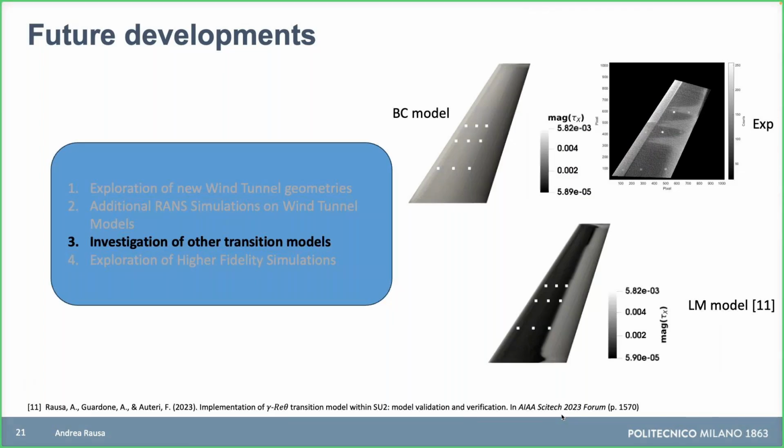Well, it depends. If you use the vortex lattice method or panel methods, then it's a matter of seconds, because they are potential theories and they do not require any other simulation. So you just have the grid. If you use the vortex lattice, you only need the mean surface, whereas if you do the panel, then you also have the thickness of the object. But it's just seconds.